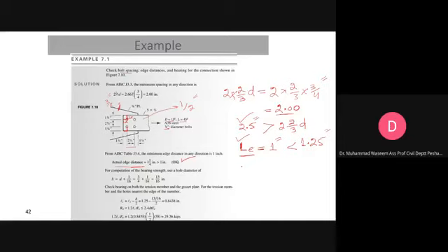Now you have to evaluate the bearing strength of the connection. For bearing strength, we have this type of formulation, which is recommended to check the bearing strength, with LC and T into FU. Now center to center distance is given, and we have to calculate LC here and LC here as well. How can we calculate LC?